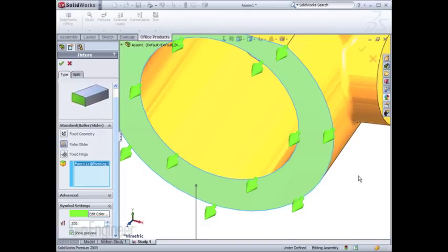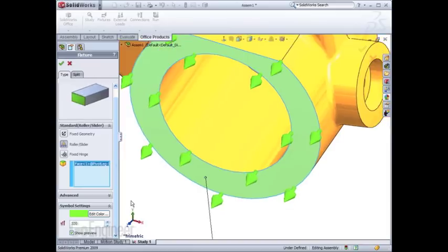you can see that translation in the Z direction is being restrained. That means we still have open translations in the Y and the X. Rotation about the Y-axis is restrained because we can't rotate about that axis if we have restraints in the Z direction on both sides of this face.